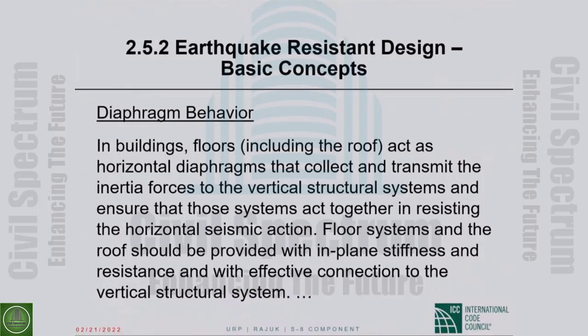Diaphragm behavior. I have 2 slides, and that's all BNBC has to say on this huge topic. In buildings, floors including the roof act as horizontal diaphragms that collect and transmit the inertia forces to the vertical structural systems and ensure that those systems act together in resisting the horizontal seismic action. Okay, we will discuss this at length. You will see what this is talking about.